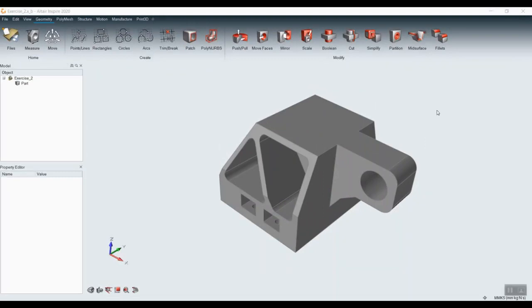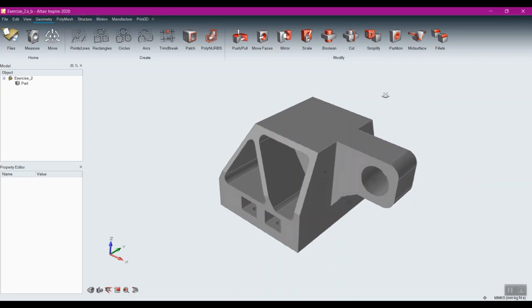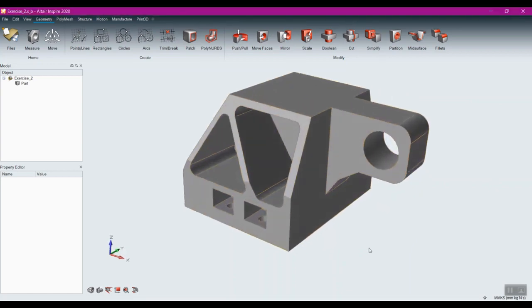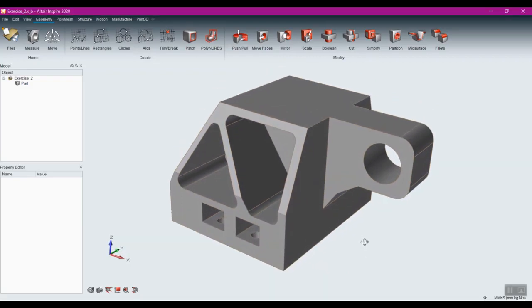The simplify tools in the geometry section of Inspire are particularly useful when we're setting up a design space. In fact, the tools that we have here are often easier to use than your CAD package. So within Simplify, you're going to find imprints, rounds, holes, and plug. Imprints are a way of you removing, say, scratches off of a part.